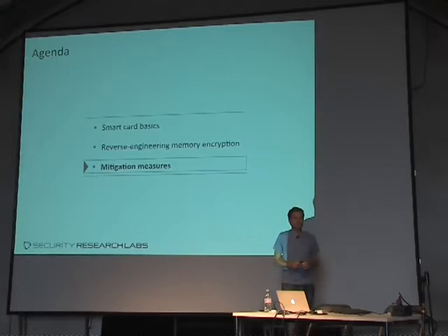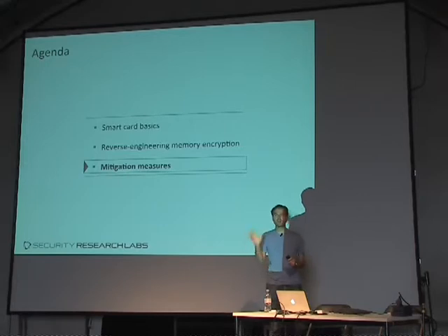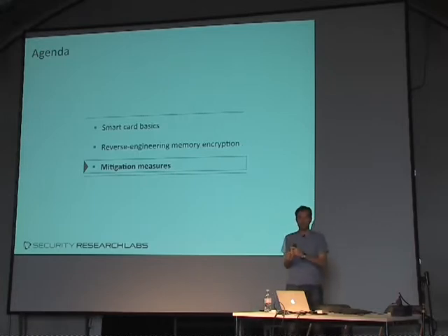We don't extract anything from EEPROM here. We don't extract anything from flash here. Those are the memories that would be used to store keys. We do extract everything that's in ROM. That's usually some proprietary operating system, an embedded Java runtime environment, and some Java applications, right?